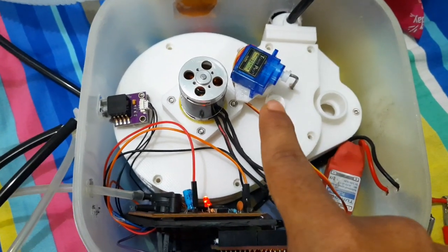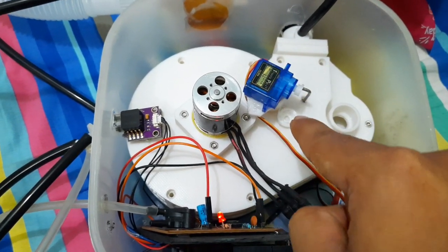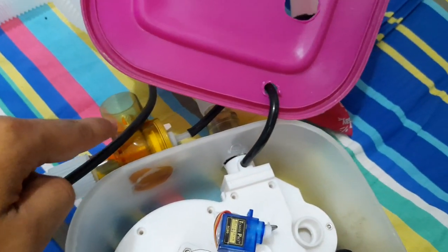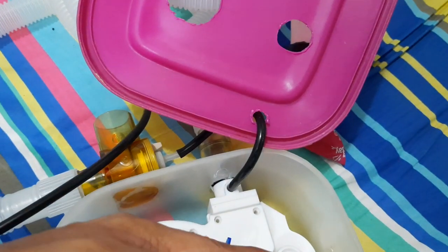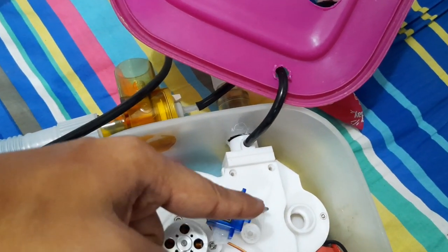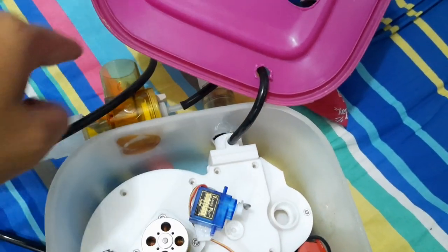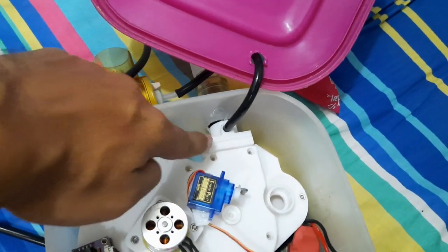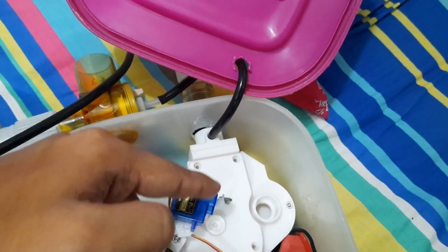Actually, in our final version I have planned to use solenoids, not the servo motor, and two solenoids for more pressure control. And one of the interesting things is this PEEP valve is actually controlled by this air pressure. So when the inspiratory line is open, that means the pressure is high, then it will close automatically, and when we release the pressure here, this PEEP valve is open and maintains the PEEP by using this air pressure.